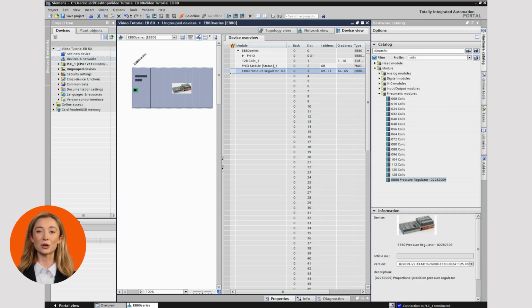The 2 bytes are interpreted as a single word that represents the set pressure value, expressed in a range from 0 to 10,000 points, equivalent to 10,000 millibars. The third input byte, instead, is the byte used to query the pressure switch, corresponding to the set reference threshold.